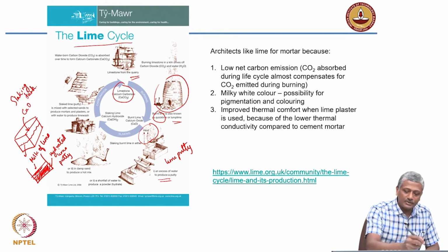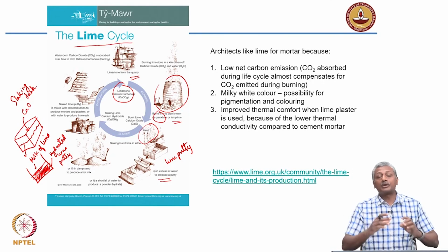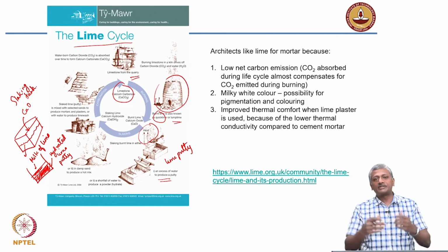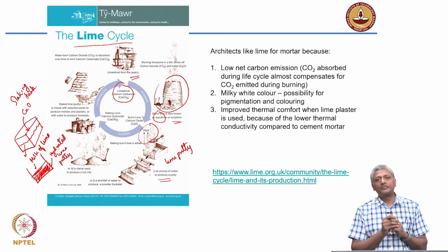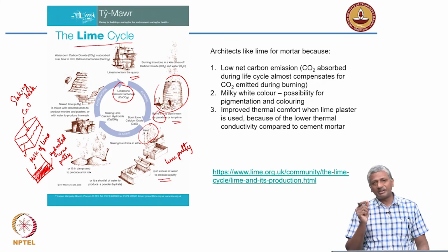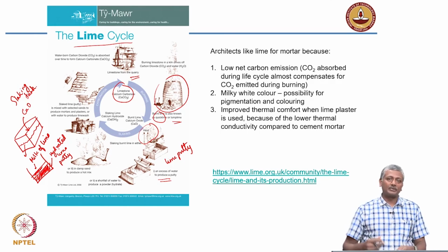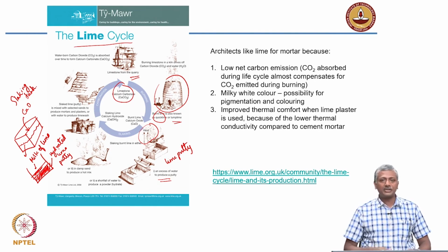Now interestingly, what has also been found is that the prolonged exposure of this lime inside the slaking tank results in very different qualities of the lime that you get for mortar making. So generally they say for plastering purposes, when you want a very fine texture to be imparted, the lime that you get has to be slaked for a long time, nearly 6 months sometimes. For binding of blocks together, the lime mortar does not need that kind of a texture. So there you can actually slake for 1 to 3 months itself.